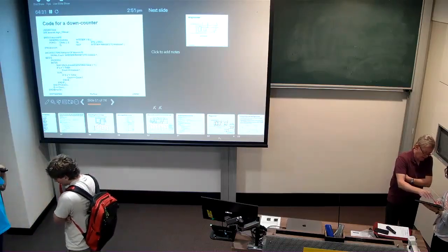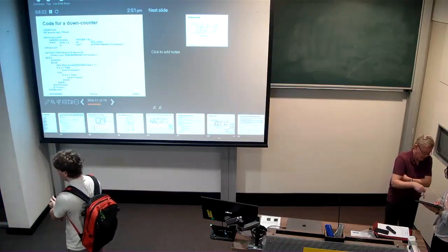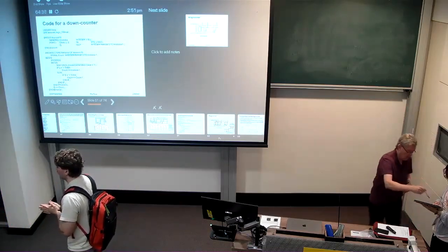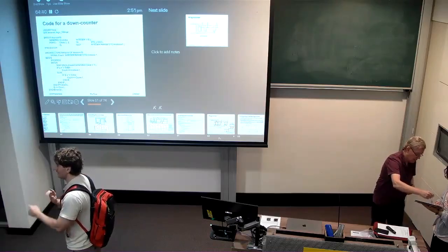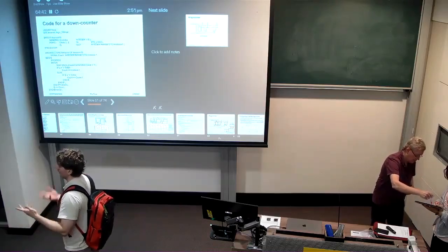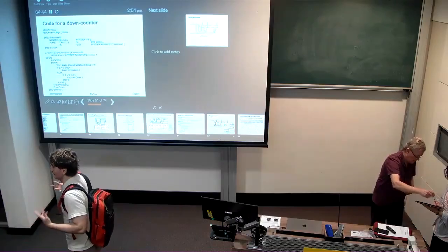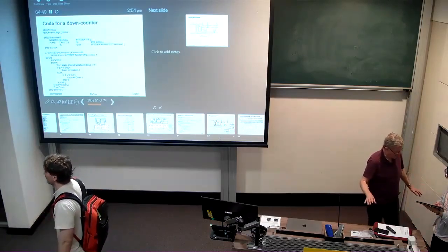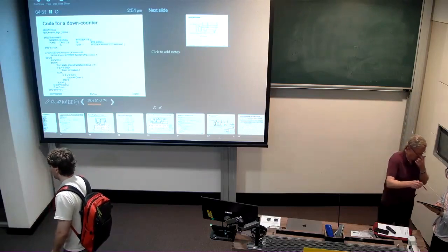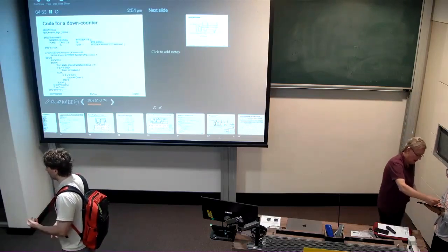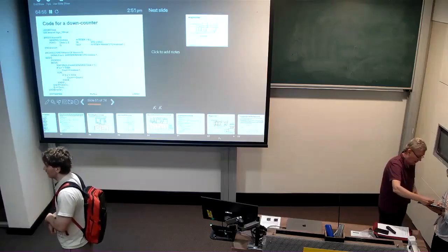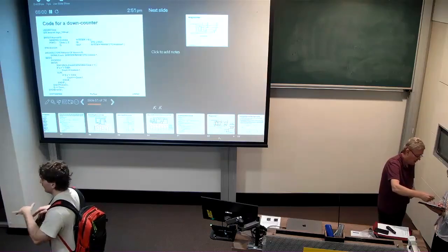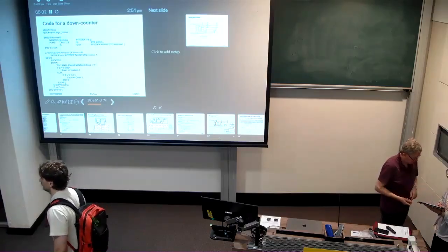If D changes at a time very close to the clock changing, then our assumption that P2 being at 0 prevents any further changes on P4 while the clock is high is no longer the case. There's a window of time between the clock going to 1 and P2 going to 0, during which any change in D is going to actually impact P4.